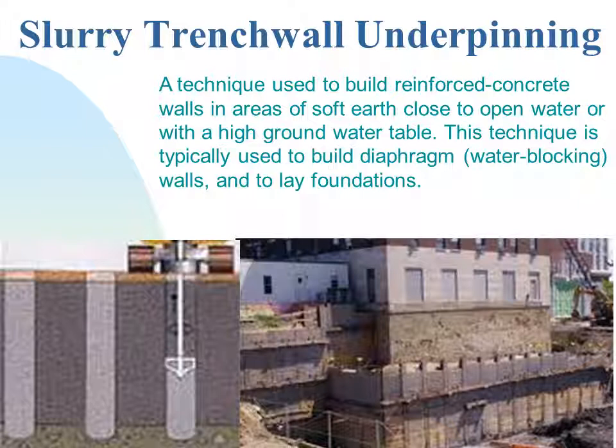These diaphragm walls will increase the capacity of the whole thing, because they will confine the soil beneath your structure. So now the foundation system as a whole became stronger. It's not a localized effect at one footing. Now you are increasing the bearing capacity for the whole foundation system.